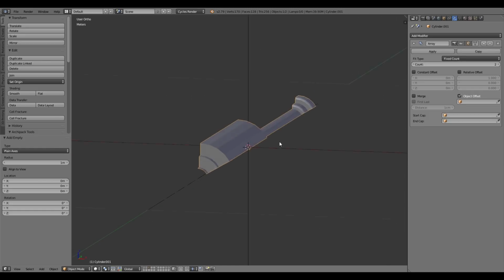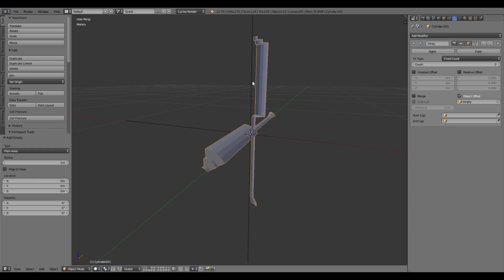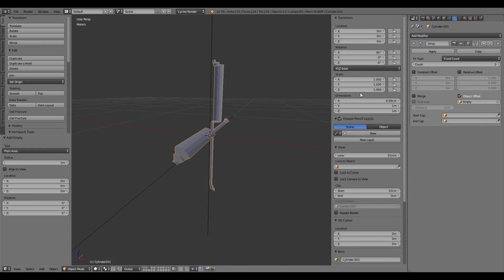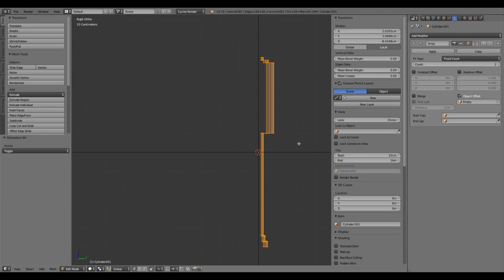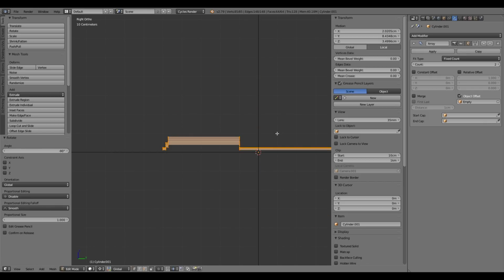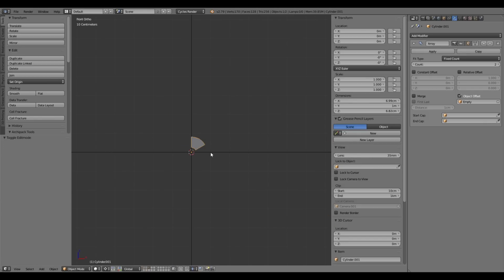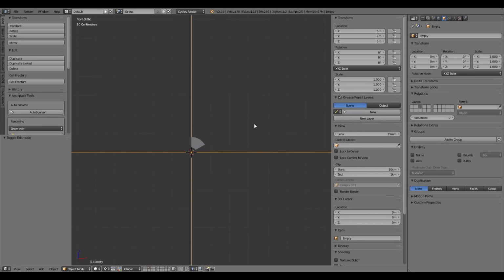Selecting that mesh again, let's just go into perspective view so we can see what happens when that gets edited. We can eyedropper this object, hit the eyedropper tool until it says object empty. There we go. Now, for some reason, it's done a really weird thing. Oh, that's because this rotation has not been zeroed out. We've got a 90-degree rotation. The way to fix this, unfortunately, is to go 0, and then it's in side view. In edit mode, we can now rotate 90 degrees that way. So now the rotation should work.